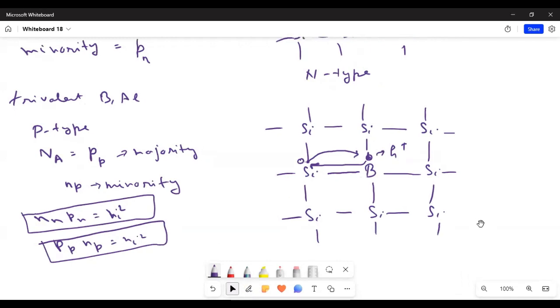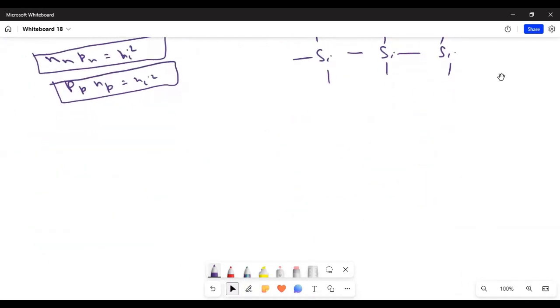Okay, so until now we see that a semiconductor has the property that we can change its charge carrier concentration and internal conductivity, how it will conduct electricity, though it is also affected by temperature. We can dope with either pentavalent or trivalent atoms and change its charge carrier concentration. We can make it either electron rich or hole rich. Basically, the majority charge carrier could be electrons or holes, and we call it N type and P type.